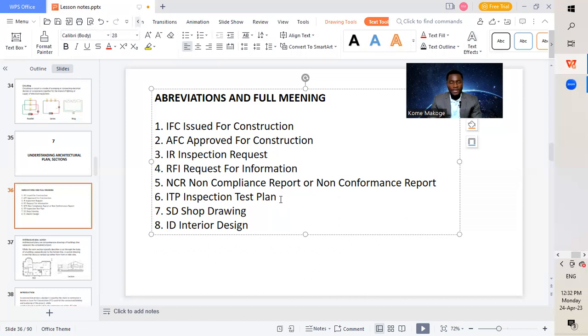So while we bring the different materials on site, we raise an inspection for that material to get approval from the consultant before we proceed with installation of the said materials. For a work as well, after a particular work has been done, we raise an inspection and get approval to proceed with the succeeding activities.